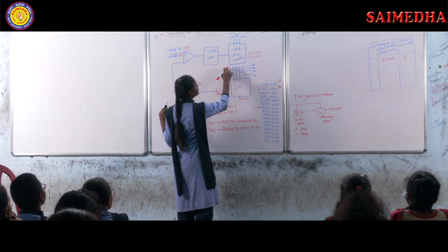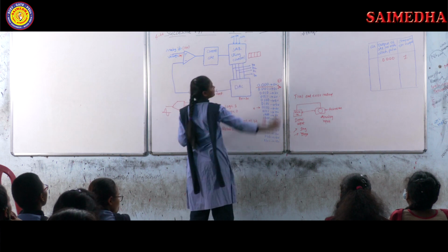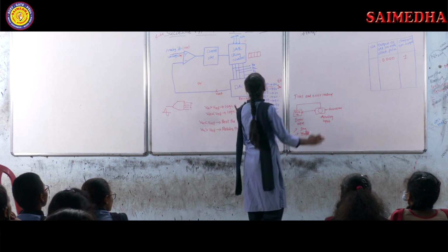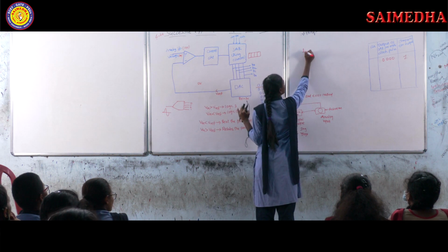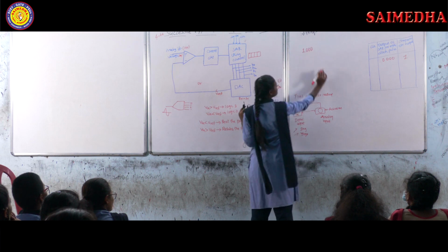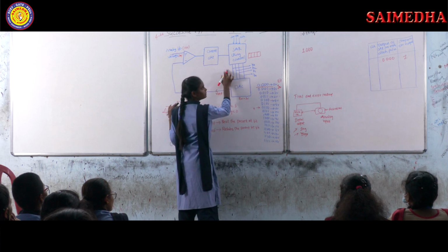And whenever we give the first clock pulse to the SAR, the MSB bit will be set. The next bits are retained as they are.